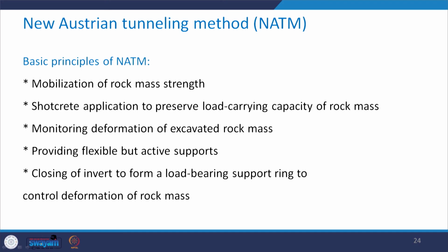The basic principles of NATM involve the mobilization of rock mass strength. All I am going to do here is summarize the salient features and principles of NATM. The first one is the mobilization of rock mass strength. We saw how this can be done. Then the shotcrete application to preserve the load carrying capacity of the rock mass.